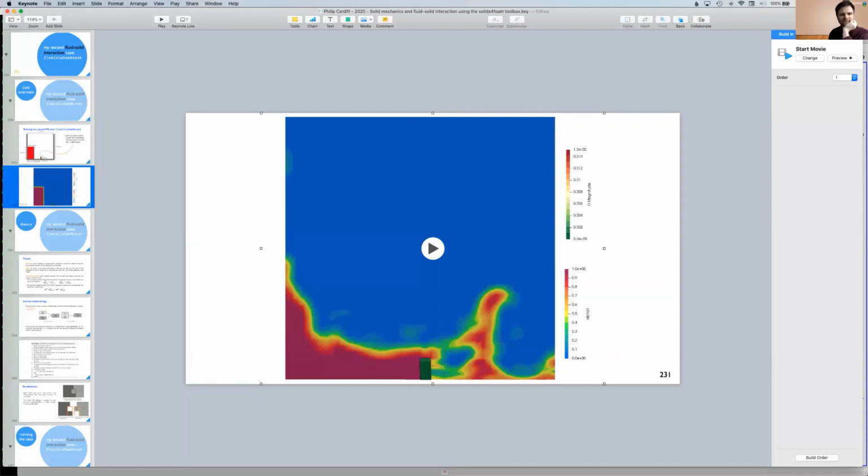When we use static mesh, does it mean that the solver assumes the deformation is very small and always solves the deformation on the original mesh? Yes, that is the short answer. If the deformation is small, that's a fine assumption. One comment is that some of the nonlinear geometry solid models have the mesh motion hard-coded into the solver, so you might see that static FE mesh is still used, but actually it's not really static. It is moving the mesh, and you see the mesh is moved. It's on my to-do list to extract that code and put it in an OpenFOAM-format dynamic mesh, just to make it more clear.